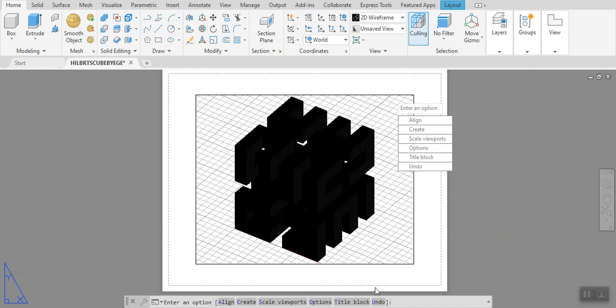And one of the things you can do, you can add a title block. Now, let me explain a little bit what paper space is. Paper space is literally what you want to put on paper. And initially, AutoCAD doesn't know what you like to have. So that's why it will offer you a window. This is called a viewport. It may be good for you, not good for you. Maybe you're going to erase it later. It doesn't matter. This is what it offers you in the beginning.